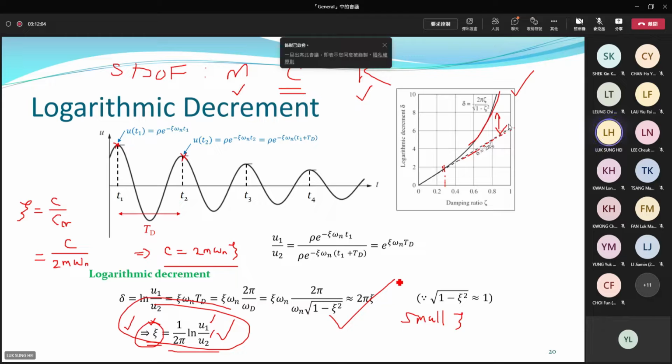So below 0.3, it seems that our assumption here is still valid. The equation is valid for this range. For this range, you can see that the two expressions are similar. But beyond this range, this assumption is not very correct. Okay? You can observe this graphically. But anyway, for this module, we normally consider a few percent damping ratio.